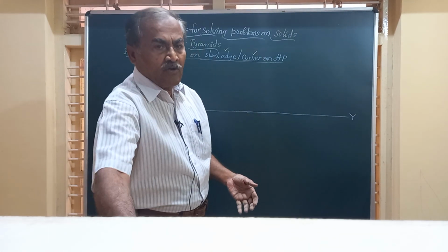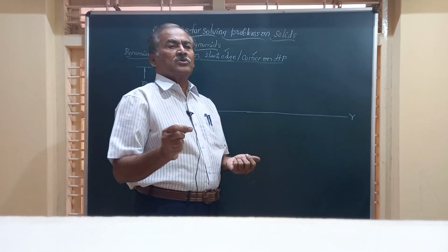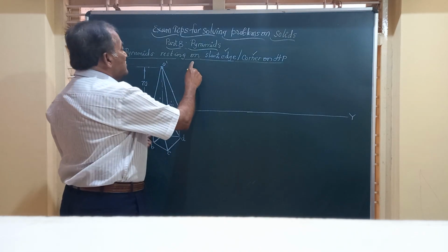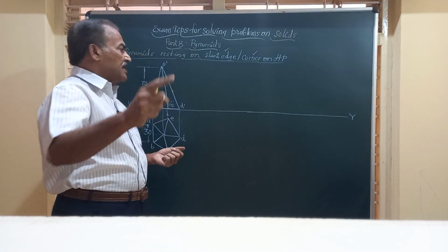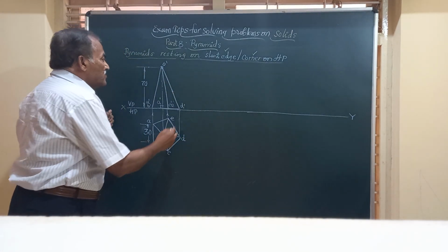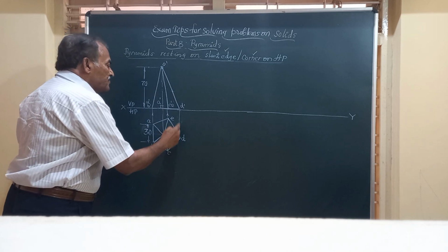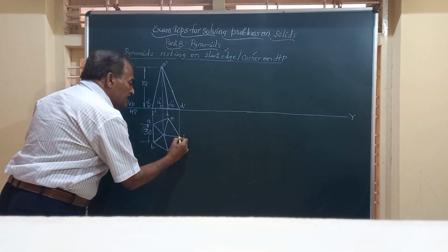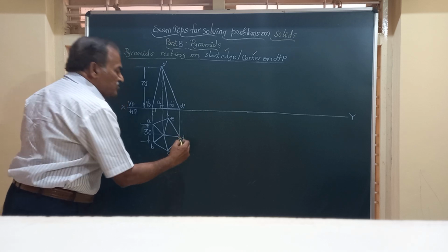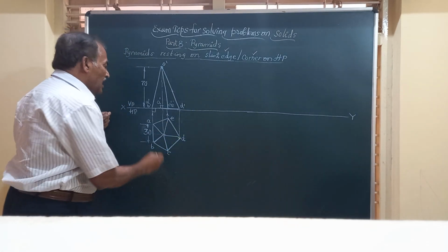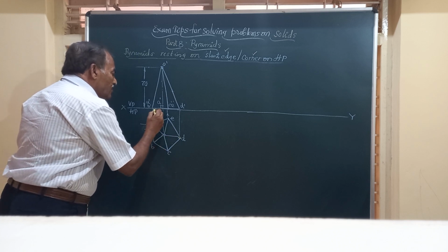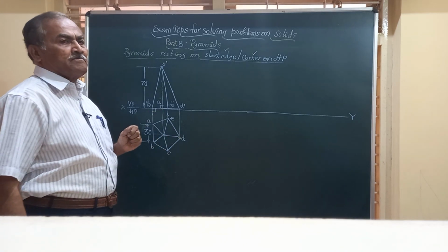So friends, now I am going to give you the tips on how to place the object. It has to rest on a slant edge. And as I told you, I have to draw the top view after placing the object such that one of the corners, say D, is to the right side of you, and the side opposite to that is perpendicular to VP.